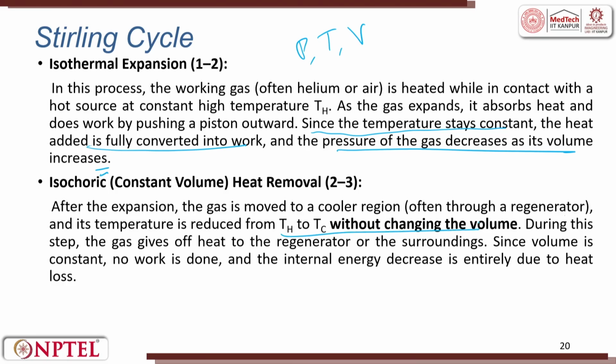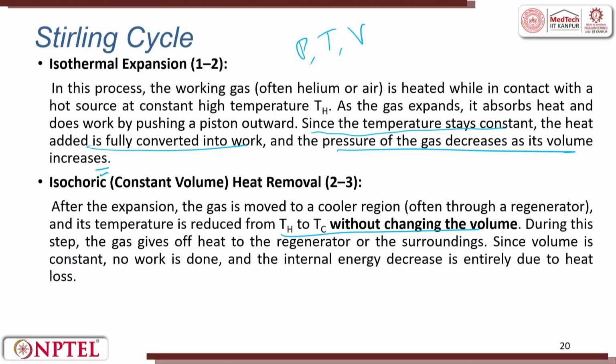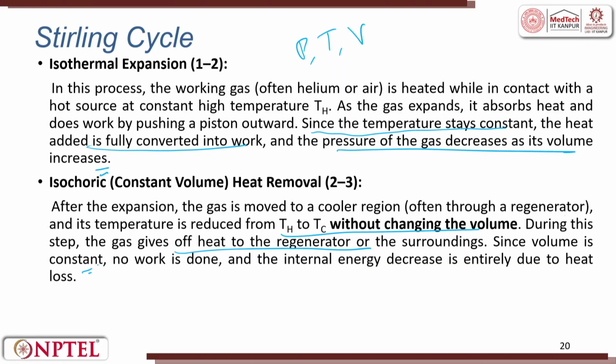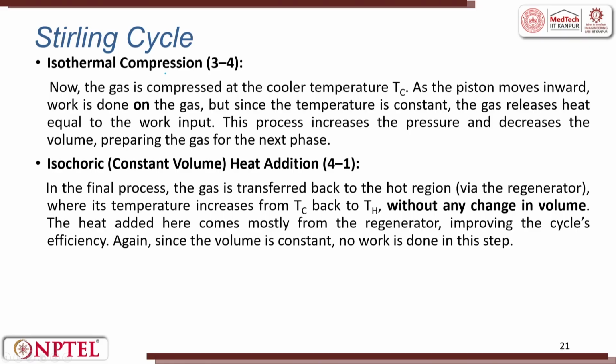So, whatever is there, it is pressed. So, there is a regenerator, the air goes to the other side. During this step, the gas gives off heat to the regenerator or to the surrounding. When it passes through, the regenerator absorbs heat. Since the volume is constant, no work is done and the internal energy decreases, it is entirely due to heat loss. Then let us go to the isothermal compression.